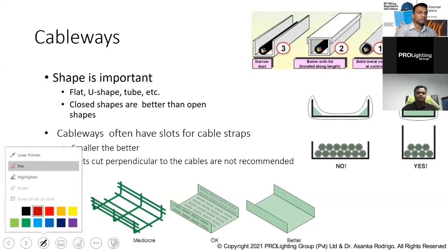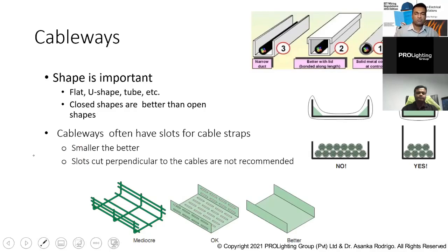Now, as shown here, rather than going with flat metal trays, it is better to always go with this type of deeper U-shaped tray, so that we get less interference. Because it is covered in three directions, rather than exposing our cable to the outside environment, if you go with this type of deeper tray, then we can reduce the electromagnetic interference. And when you look at the different options, the best option is to put these sensitive equipment or cables inside round metal conduits.